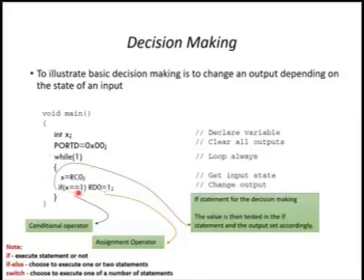So for example, first you declare the variable, integer x, and then when the condition is true, you begin to execute this continuous looping by displaying the value of x in port D, and then you increment. You can see here, double plus. If x's initial value is 0, you increase it to 1.